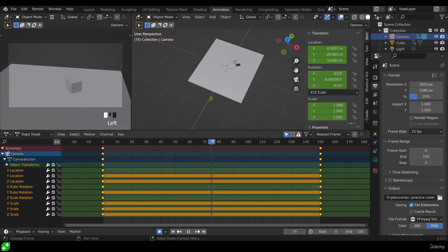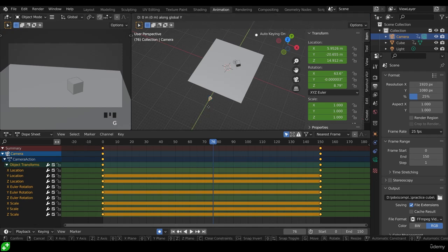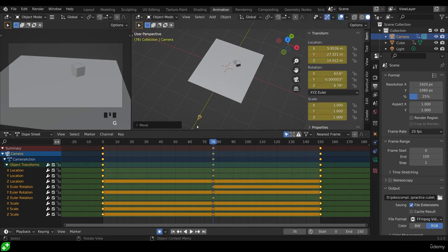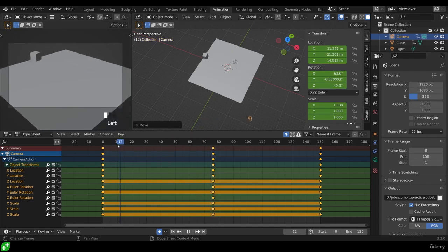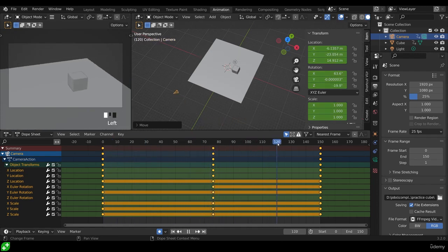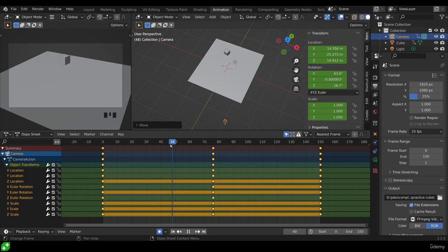If I go to frame 75, you can see it's slightly zoomed in here, so I need it out here somewhere. So I can press G then Y at this point, so it zooms out slightly, and again, I've got the record button on, so it's recorded that movement. I wasn't quite on frame 75, I didn't notice, but that doesn't matter too much. And we can see we've got a slight curve to the animation now. So you can see there we can animate the camera as well.